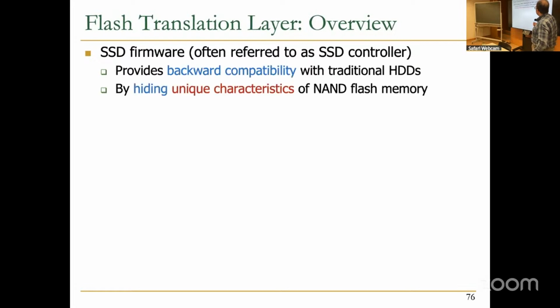We discussed this flash translation layer, which provides backward compatibility with traditional HDDs. That's one of the important tasks of the FTL or SSD firmware, to provide that backward compatibility for you. That happens by hiding a lot of characteristics of NAND flash memory.